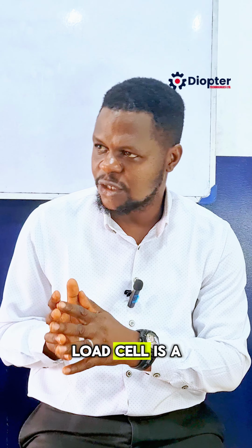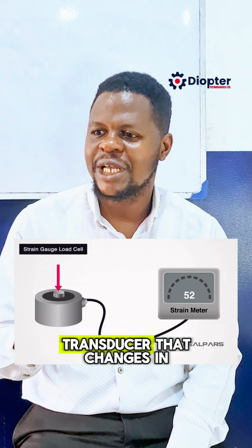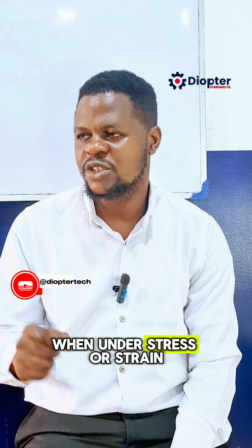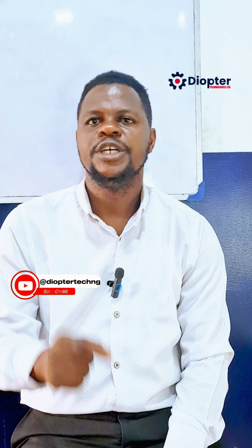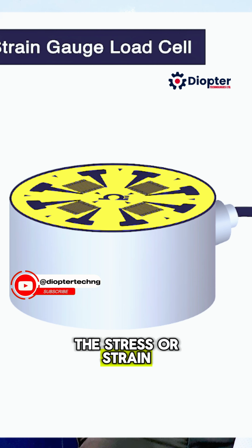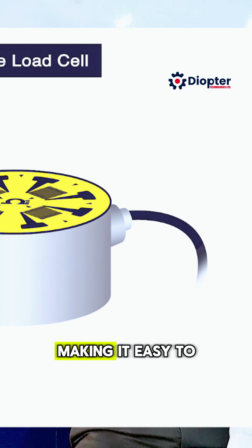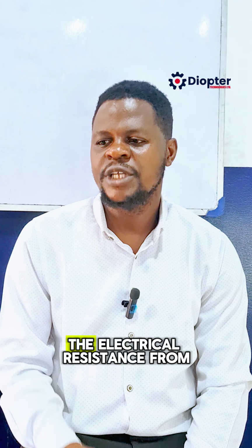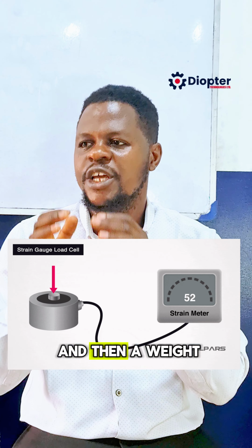A strain gauge load cell is a transducer that changes in electrical resistance when under stress or strain. The electrical resistance is proportional to the stress or strain placed on the cell, making it easy to calibrate into an accurate measurement. The electrical resistance from the strain gauge is linear. Therefore, it can be converted into a force and then a weight if needed.